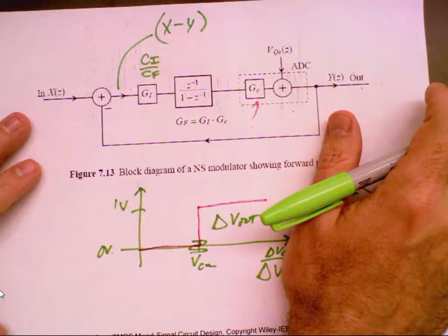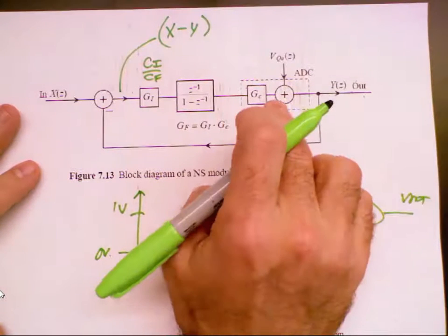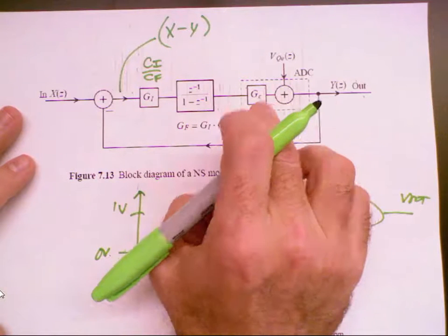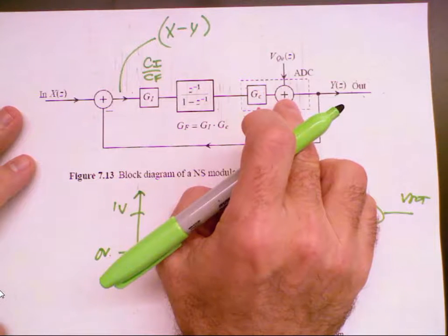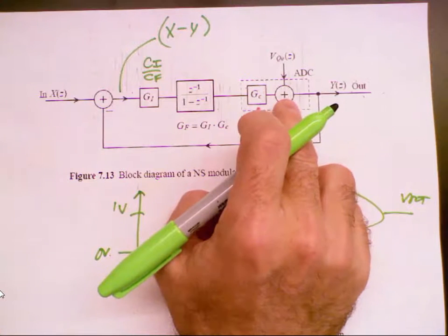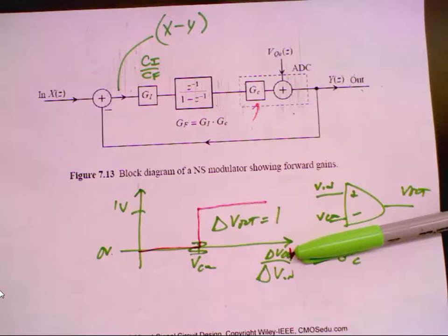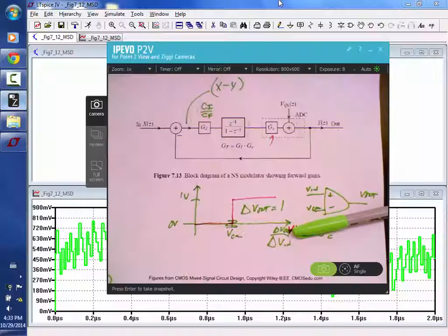Yeah, the problem is that if you're using a clocked comparator and you want to find the DC gain of the comparator, it's really tough and you need to move your input really slowly, because if you do like the sim I put in there, there's a granularity in the clock size. So it could pass the threshold, but then you don't clock the comparator until 7 nanoseconds later, and then it looks like there's a big offset. Do you follow what I'm saying?